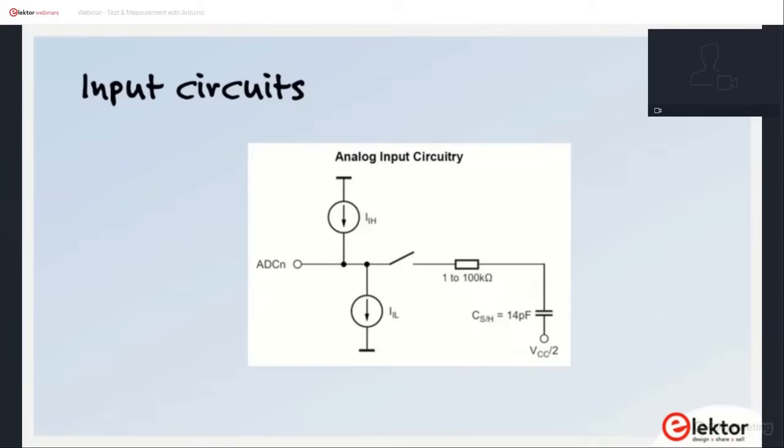The ADC inputs are optimized for signal sources with an output impedance of approximately 10 kΩ or less. They are not high impedance inputs as found on oscilloscopes and multimeters. It may therefore be necessary to insert a buffer between the signal of interest and the ADC input to avoid influencing or even destroying the input signal. As already briefly mentioned, analog inputs may need an anti-aliasing filter to improve the results, especially when signal frequencies get close to half the sample rate, which is about 4.5 kHz.